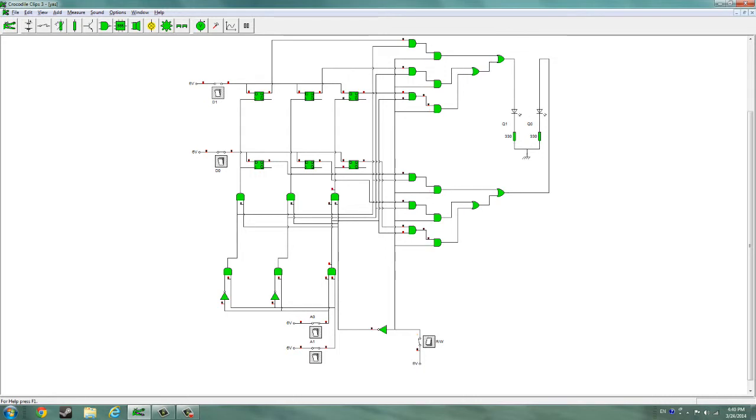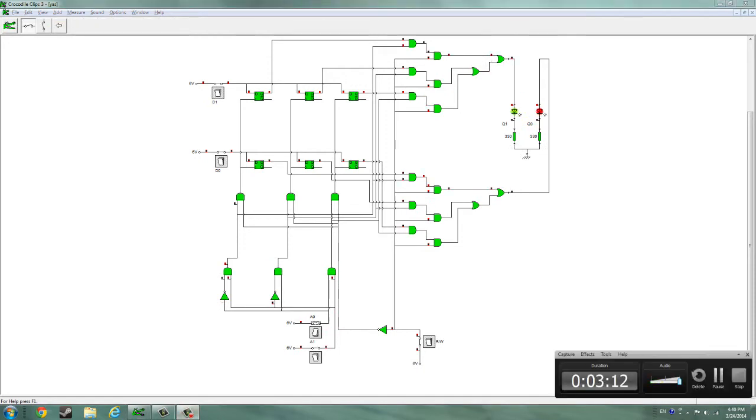If we wish to see what was saved, we set the circuit into read mode. In read mode, D0 and D1 switches are irrelevant. And also, you can see what's saved in each memory cell by navigating through the address leads. Currently, there is only 1, 1 or 0, 0 saved in the other address leads. But you know what? Let's try the circuit out in real life.